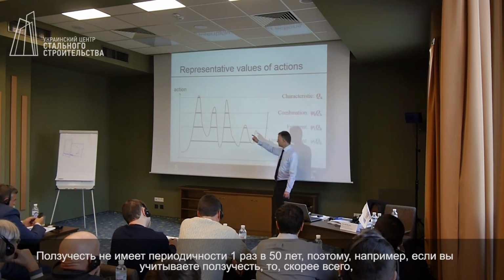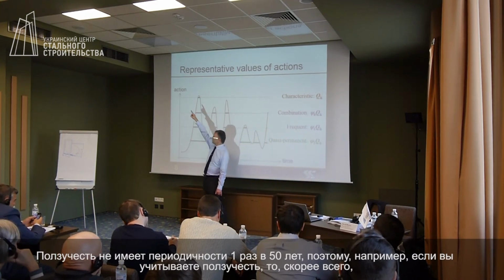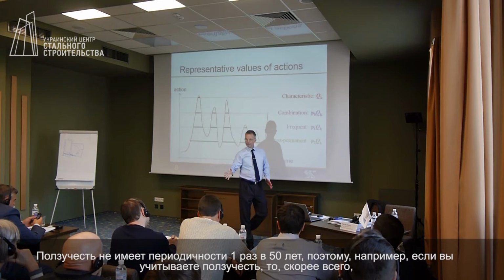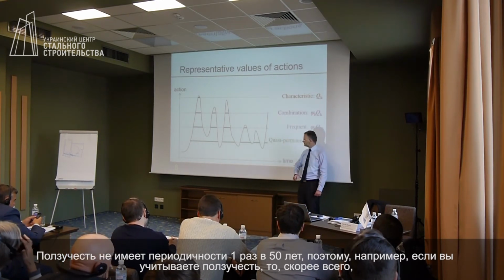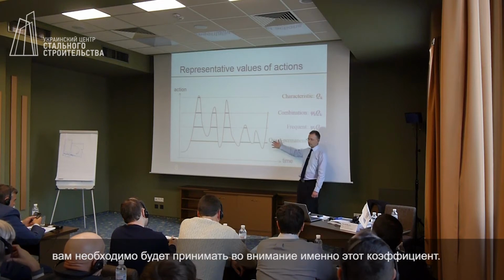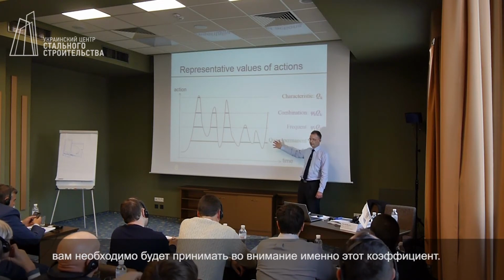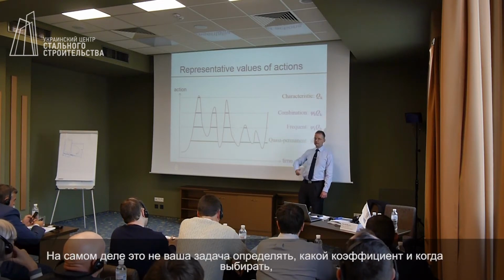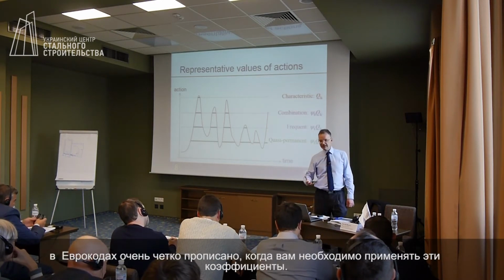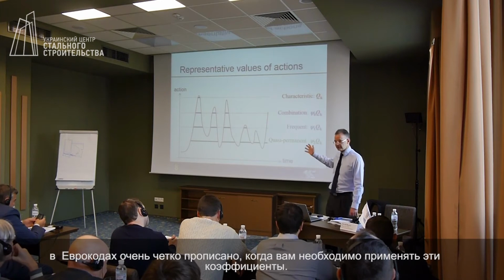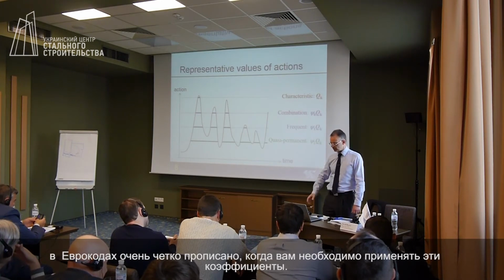Creep is not interested in the 1 in 50-year event. So if you were considering creep, or the permanent deflection of concrete, then you would probably be interested in this value. It's not for you to choose, ladies and gentlemen. The Eurocode defines exactly when you should use these values, and we'll go on to look at those.